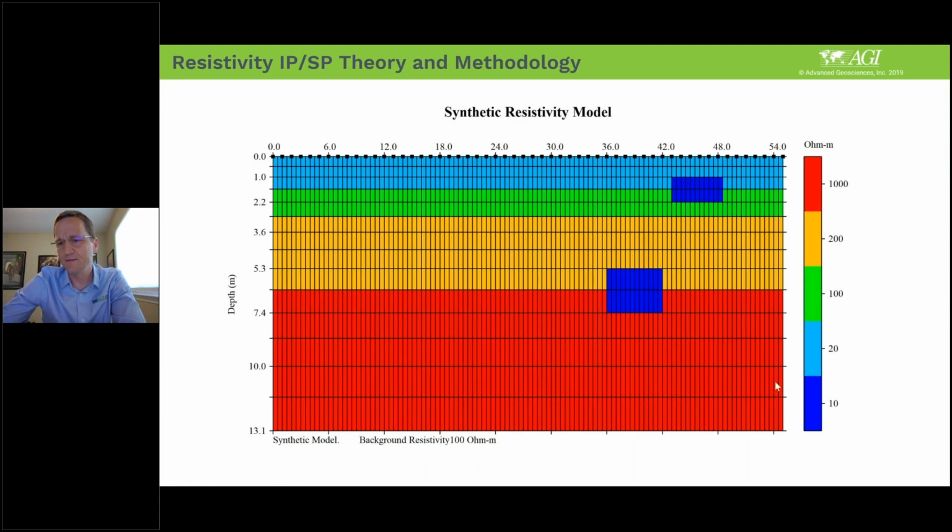Now, if we were to add a clay lens off to the side here, like you see, okay, yeah, so this is 10 ohm-meter pockets, and this is very common to have mixed soils, unless it's all engineered materials. But in earth systems, you very often have mixed soils, you have void spaces, things along those lines. And if you were to run a Wenner sounding over this area, say from A spacings from 1 foot to 30 feet, that would cover that.